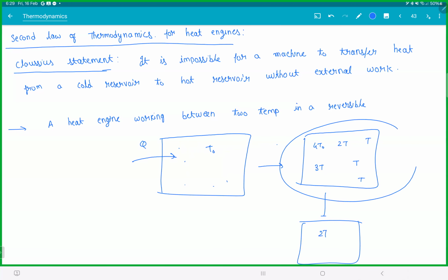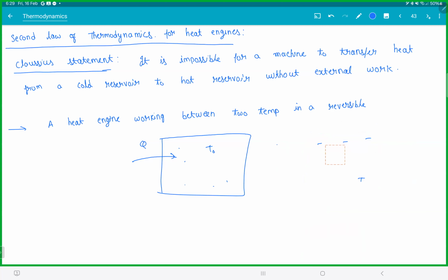So during this stage, is the temperature defined? Temperature is not defined. Getting it? So that means we can't use ideal gas equations. So what we assume is, instead of saying we are giving so much heat, you are giving such a small heat dq, dq, dq. We are assuming the whole compartment is increasing by T plus dT, T plus 2dT, T plus 3dT. So we are assuming at every instant the system is in equilibrium. Such a process is called a quasi-static or reversible process. Clear? That's it. There are no questions on that. That much idea you should have.